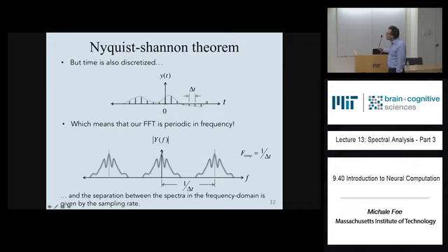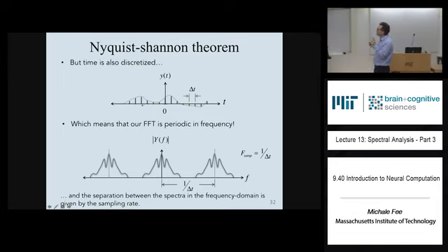It's really one period of a periodic spectrum. Mathematically, if our signal is discretized in time, it means the spectrum is periodic, and the FFT algorithm is passing back one period. And then we do this circular shift to get this thing. That make sense?